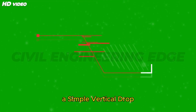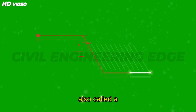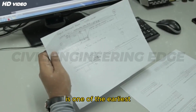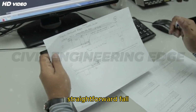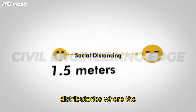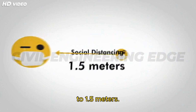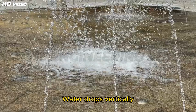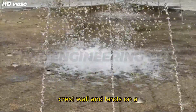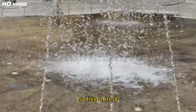Segment 6. Design of a simple vertical drop fall. The simple vertical drop fall, also called a rectangular drop fall, is one of the earliest and most straightforward fall structures in canal engineering. It's used in small distributaries where the difference in bed level is minor, typically up to 1.5 meters. Structure: water drops vertically from a raised rectangular crest wall and lands on a horizontal concrete or stone apron, where energy is dissipated.